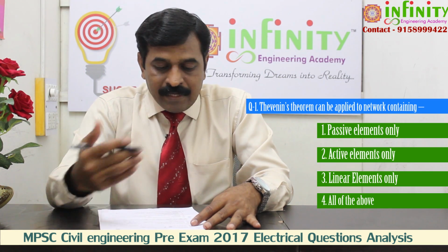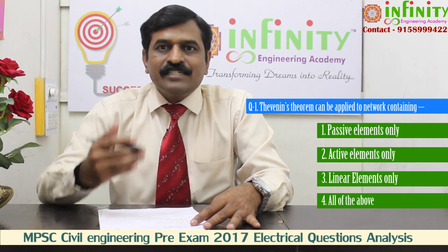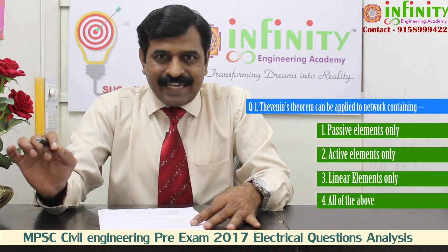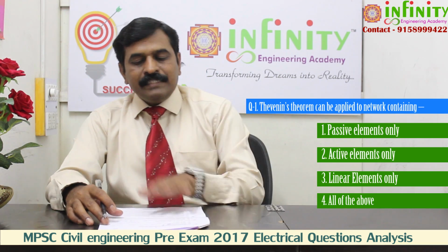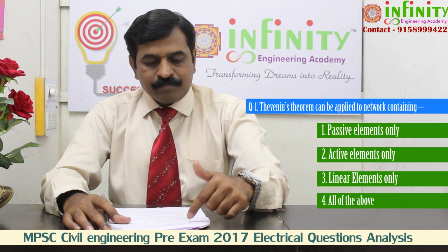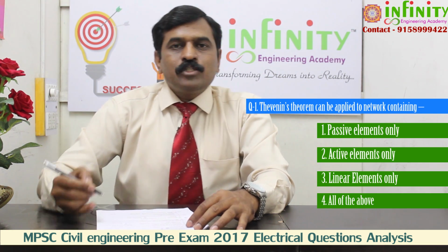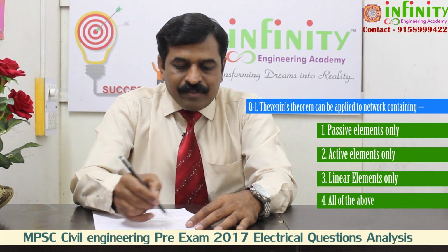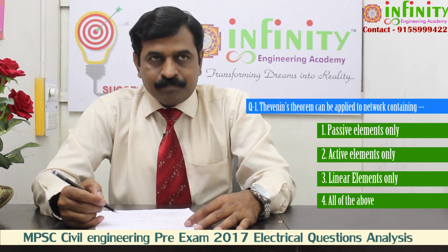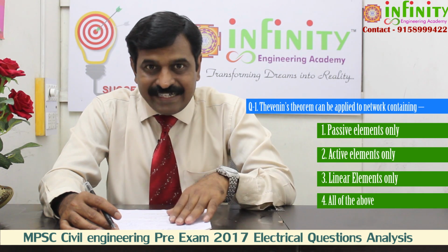What are active elements? Active elements are those elements which can produce a gain, such as transistors and diodes. Again, it is not a correct answer, because Thevenin theorem is not applied only to a network which contains only active elements. The third one is linear elements only. What is the meaning of a linear element?